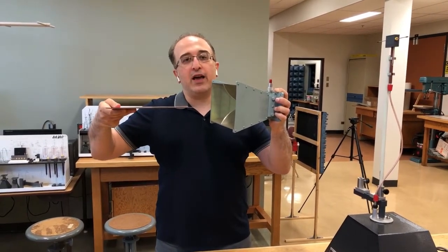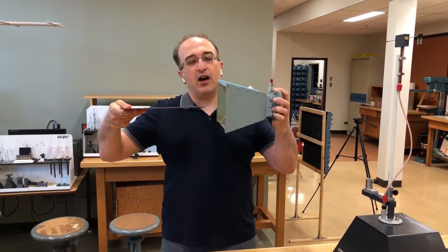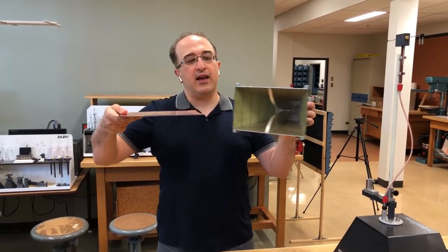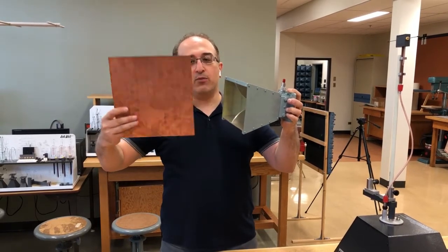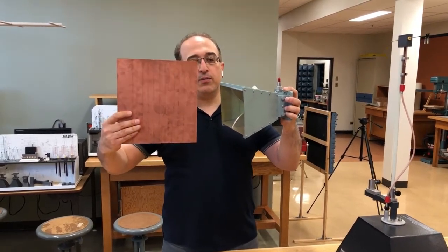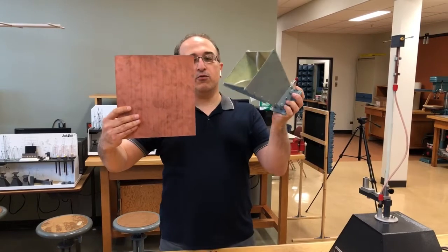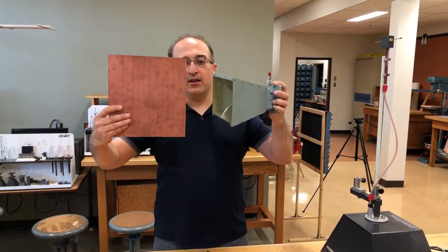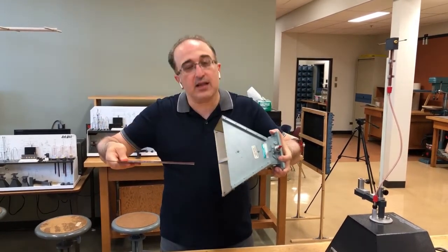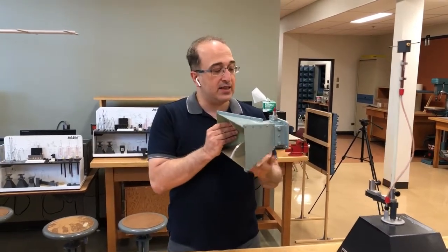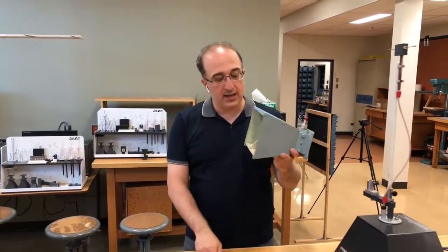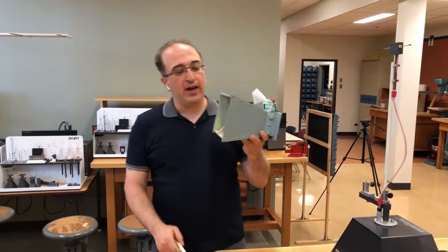Now, if I want to do H-plane measurement, I'm going to rotate it in the H-plane like this, right? To do E-plane measurements, instead of moving like that in the E-plane, we rotate the whole thing like this and perform our E-plane. Now, let's go to a little bit more detail. Let's assume I want to do H-plane.